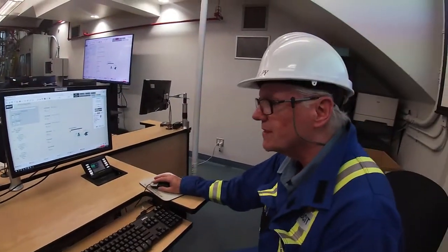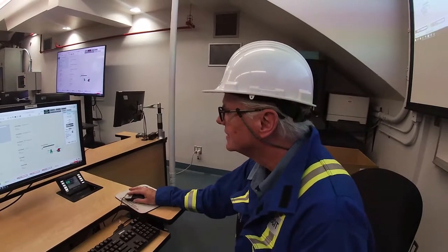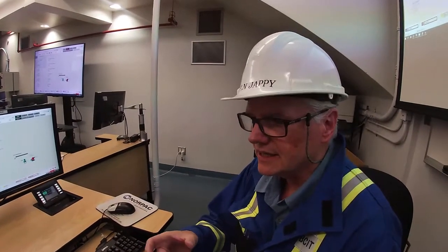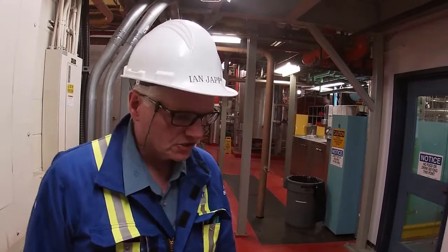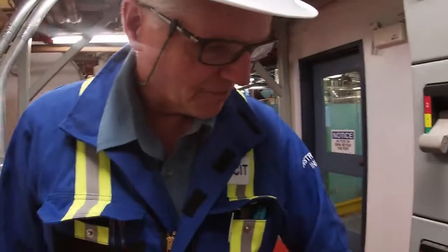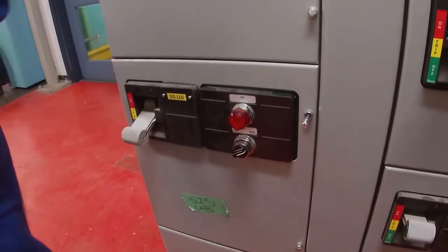So what I'll do is I'll stop that pump, and we'll have a look at that contact that's in the starter. There's a relay in there, and we energize that relay from the SIS, and then it closes the contact on the starter circuit. I'll go through the starter circuit with you. Okay, so our pump that is upstairs, and just so you know, we actually haven't pulled the cable to the pump yet. We've got to get the electricians to do that for us. But we're simulating the start-stop here. We just don't have the T-leads connected for that cable.